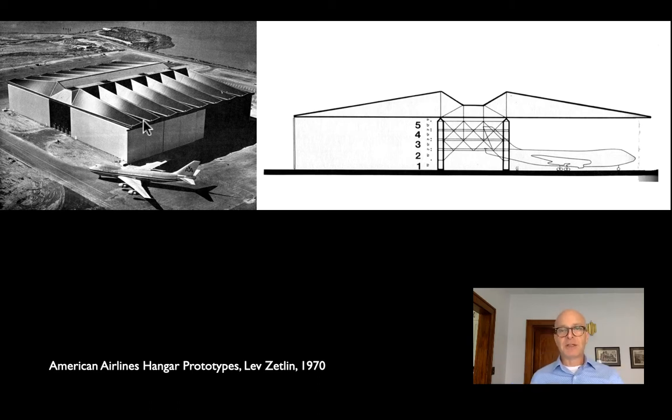And again, if you look at this in profile, what you can see is that we have a cantilever shape deep over the root, skinny at the end, but that cantilever shape is just made up of very, very thin corrugated steel sheeting. And so you get all of the depth of that shape, but you're reducing almost all of the weight. You're taking out almost all of the weight of that solid cantilever, and you're basically making it a hollow shape.